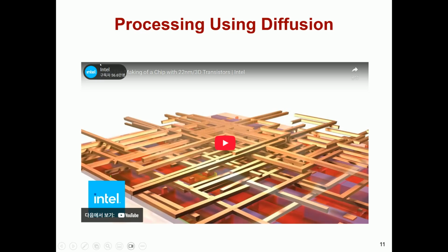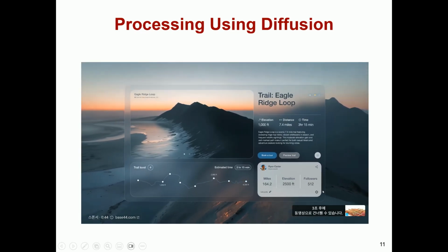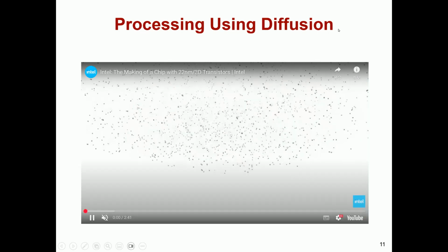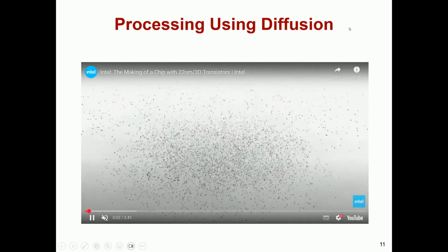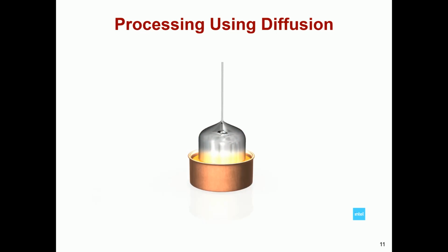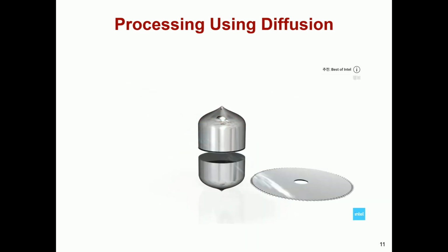Since we discussed semiconductors, I should explain the fabrication of this process. So, semiconductors start with sand. I'm going to skip it for a few seconds. Semiconductors start with sand, silicon dioxide. We apply intense heat for purification and solidification. Critically, we must produce a single crystal wafer, not polycrystalline material. This is not an easy process.